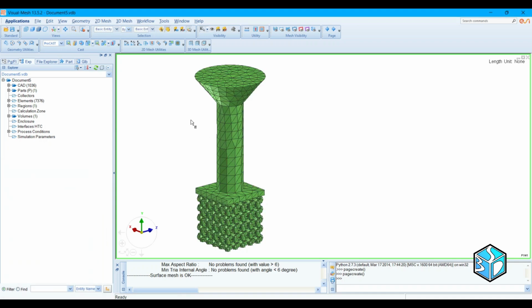In terms of doing an investment casting simulation, you need to create and prepare a shell as a mold, which we actually call refractory alumina in the real world, and we are going to assign this material to the shell part in the simulation too. But we couldn't import and create the shell in SolidWorks or different kinds of CAD software, so we need to create the shell in ProCAST software.